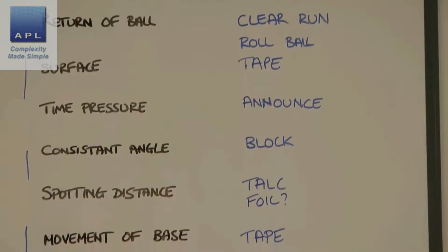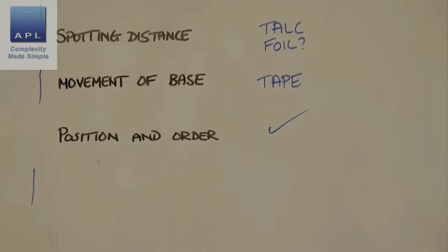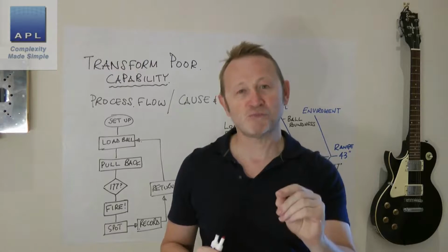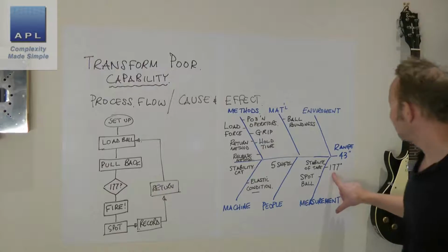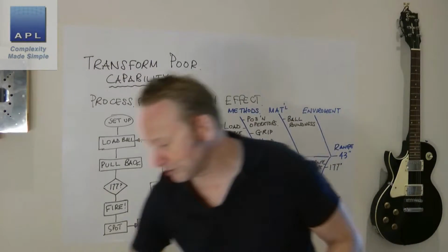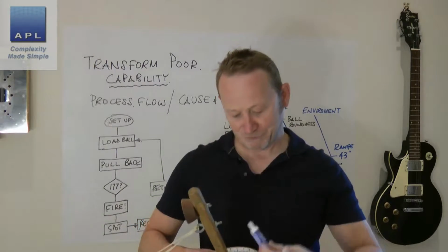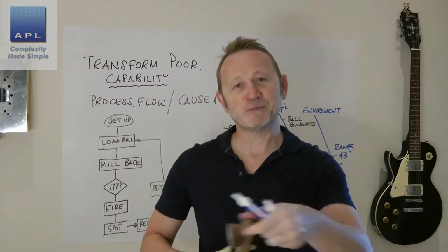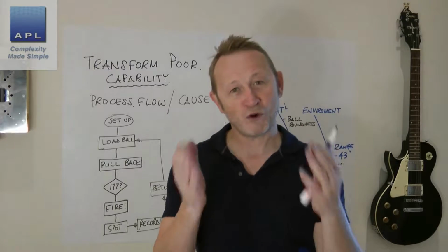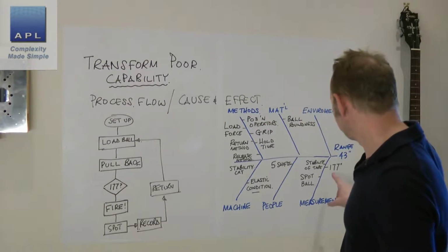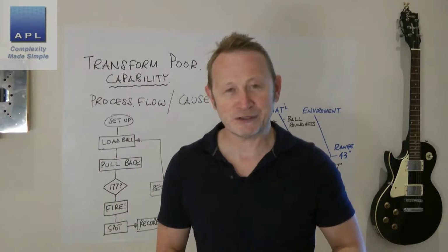up with a method, a standard, an agreed way of reducing the variability to as small as it can possibly be for that variable. So for example, for the 177 degrees at the back of the catapult here, what do most groups do? They simply find a nice hard stop and they pull it onto a nice hard surface, and they're guaranteed 177. So some of the solutions almost eliminate the variability. So suddenly we've got no variability in the pullback angle.